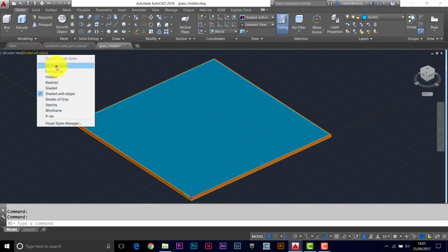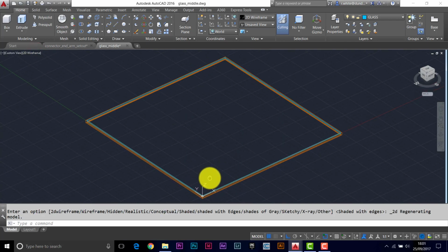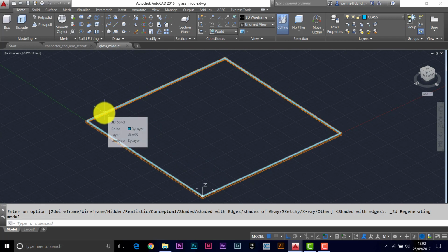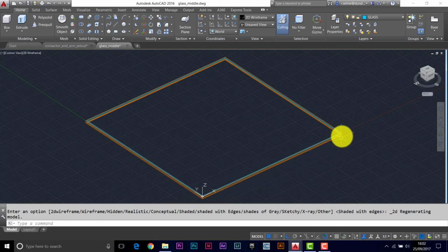Where do we cut the holes? Okay, and how many holes do we cut? Okay, the piece of glass that's next to the ground, if this were the ground line here and if this glass was upright, you wouldn't have holes in the glass next to the ground, but you would have them at the top. So there needs to be two variants of this panel, one with 2 holes and one with 4 holes.